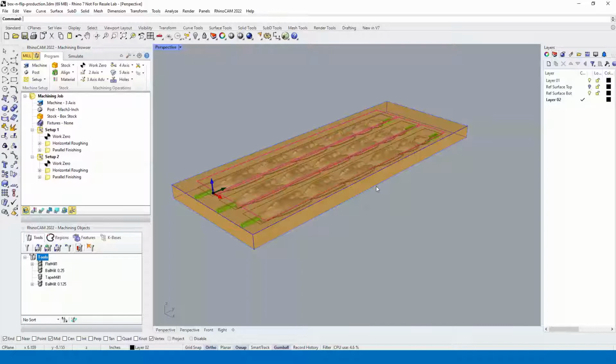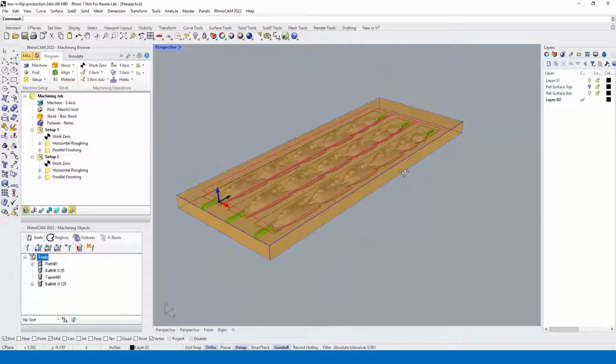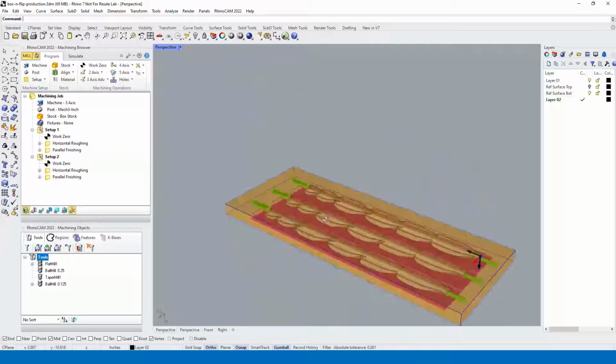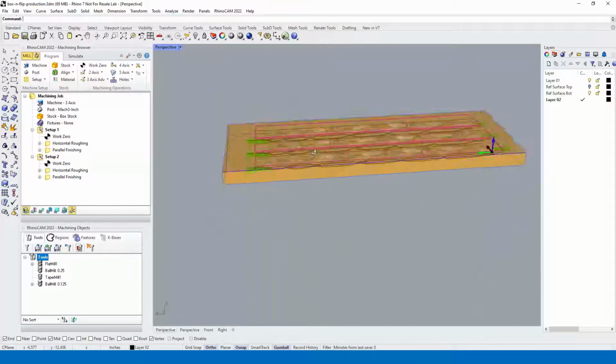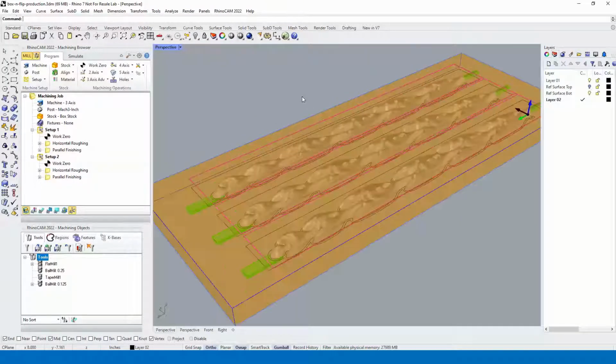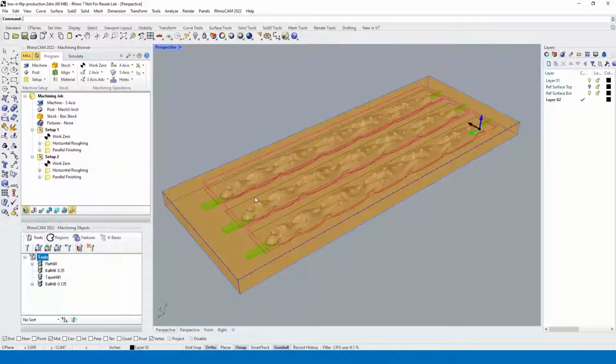And in this example, I showed you the picture of the cut material simulation. Basically, you're doing the same. If you have the extended configuration, you can only machine one side. Then you'd have to physically flip it over and machine the other side. So you can see here in an actual real world example where it makes it a lot easier in the Pro configuration to actually machine both sides. And we could go ahead and simulate it, but I've got a more complex part I want to bring up and make sure we review that as well.